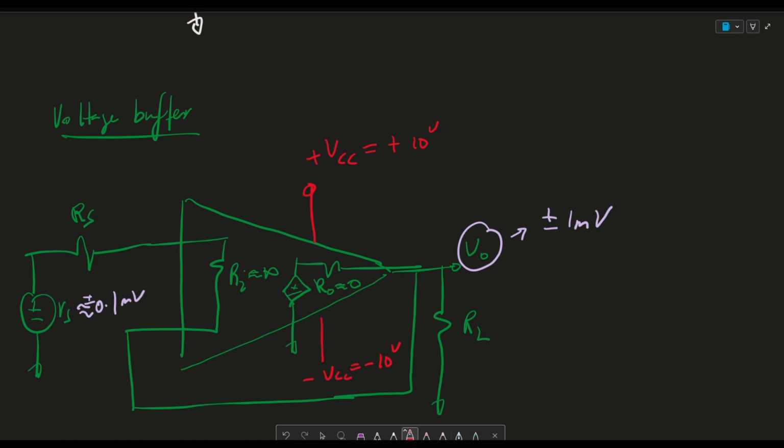But we say that, okay, the current going in here, let's call this, so this is the positive terminal, this is the negative terminal. IP is extremely close to 0 because, again, this resistance is extremely big. So it's acting like an open circuit. So no current is going to want to flow through there. And the current coming out, IN, is extremely close to 0. So that's where we get IP is essentially IN, which is equal to 0.